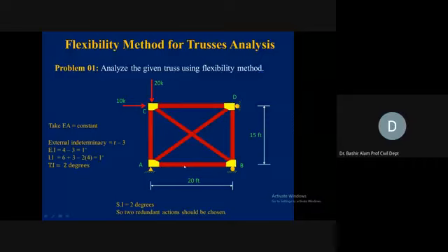Now cutting member, if you see, you can cut AD. If we remove this member AD, we still have a very nice triangular arrangement of the members. Let's say AD is removed. So we have the triangle ACB, and then we have the triangle CBD. Or you can remove CB, still we have the triangular arrangement, so it will be the truss configuration and the requirement will be met.